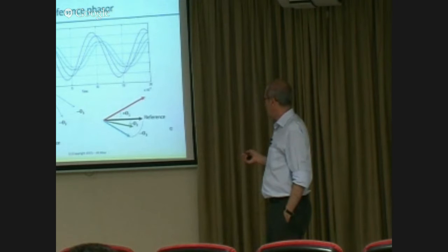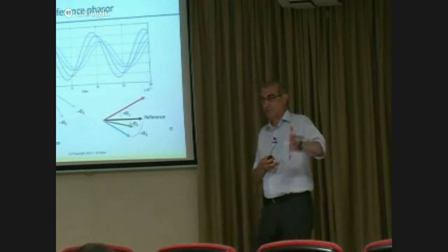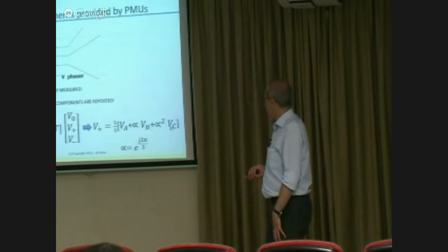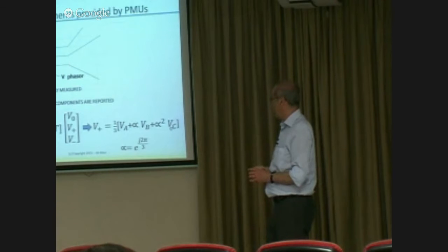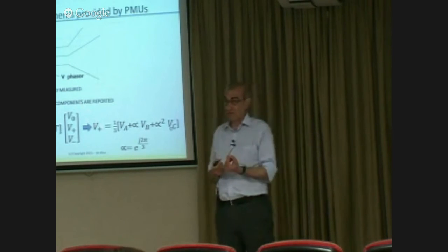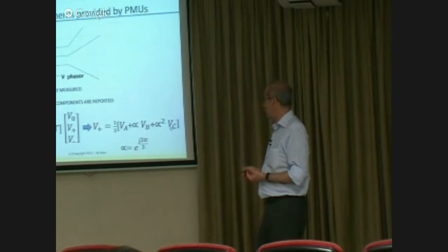So you basically come up with a bunch of phasors, which are implicitly assumed to be referenced with respect to this GPS. Of course, we monitor all three phases, but we convert them into positive sequence, and we actually only receive the positive sequence voltages and currents from PMUs, phasor measurement units. These are some of the details of how we receive this synchronized data.